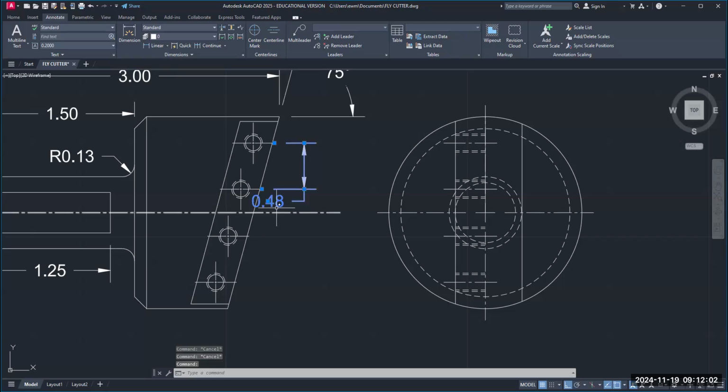All right, now watch this. Click on the number or the dimension and you can hit F8 now. If you hit F8 as you're doing this, I'm going to do it again, right? I'm going to undo it, watch. See, if I click on this, it's very cumbersome trying to move that dimension. I can come out this way, or it's very hard to move. If I hit F8, now look, I'm going to place that dimension text right there.